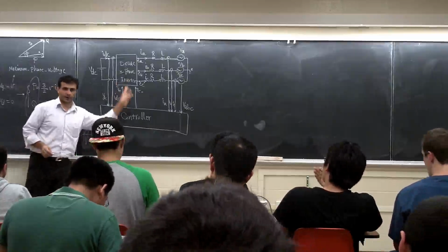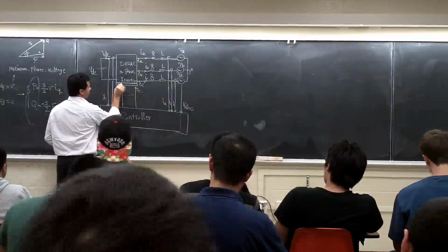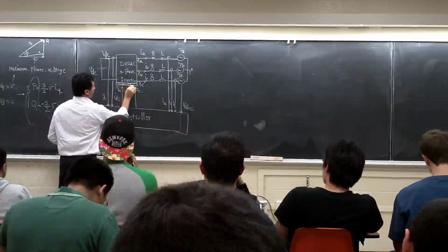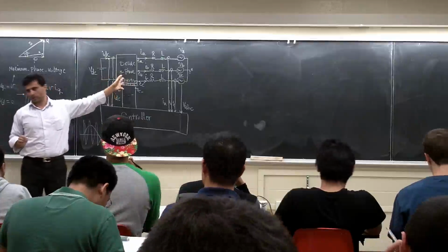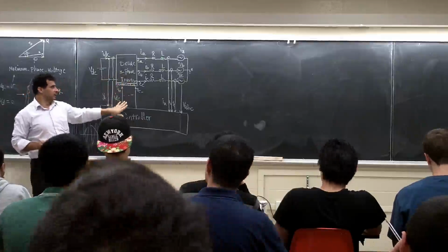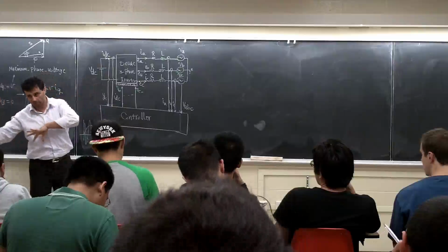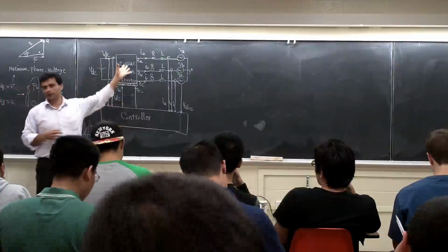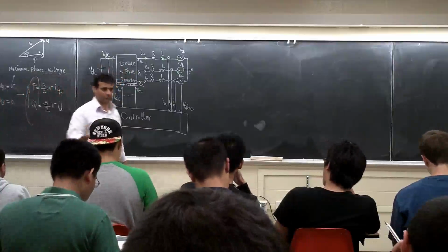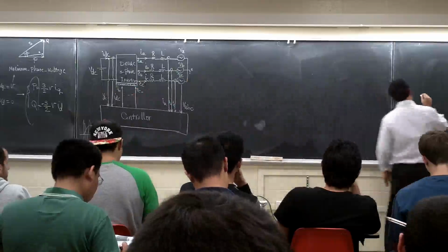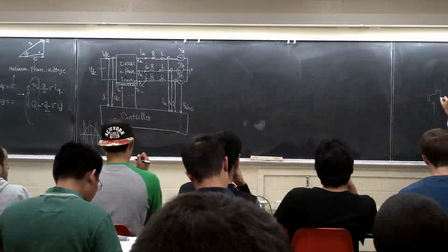Those on, off signals are going to come here. Usually these inverters have one interface board, they call it the gate drive. This control signal goes to another board. I'll bring one inverter maybe next week, and you can see all these things. All these signals go to the gate driver, and the gate driver is going to change this control signal to a power signal, right? And then connect it to the IGBTs, and start to turn the switches on and off. In a PC also, if you look at it, when you have a switch, right?